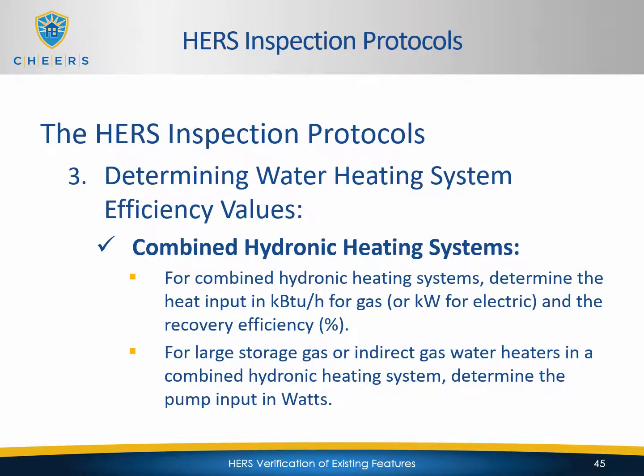For combined hydronic heating systems, determine the heat input in kBTUs per hour for gas, or kW for electric, and the recovery efficiency percentage. For large storage gas or indirect water heaters in a combined hydronic heating system, determine the pump input in watts.